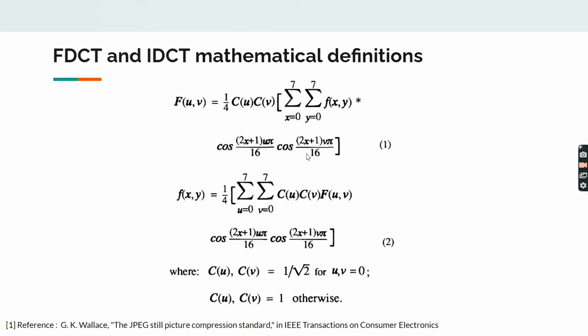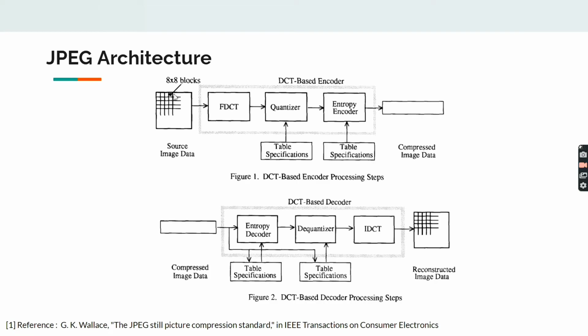Encoder FDCT. Each 8x8 block of source picture samples is a 64-point discrete signal that is a function of the x and y spatial dimensions. Because sample values typically vary slowly from point to point across an image, the FDCT takes such a signal as its input and decomposes it into 64 orthogonal basis signals called DCT coefficients, whose values are uniquely determined by the 64-point input signal. For typical 8x8 sample blocks from a typical source image, most of the spatial frequencies have 0 or near 0 amplitude and do not need to be encoded.